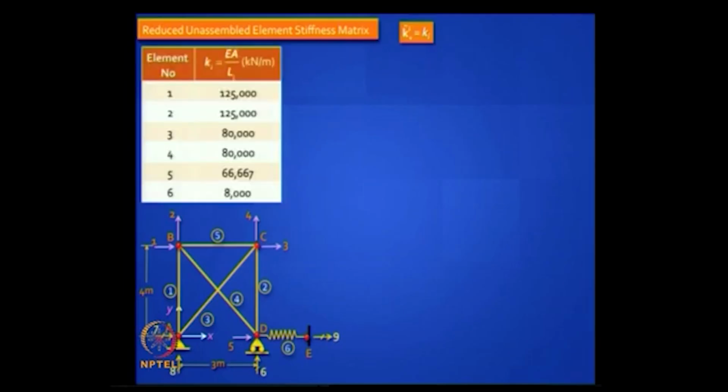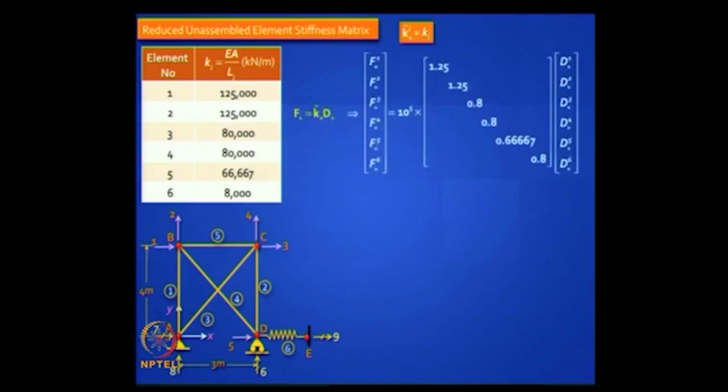So now you have got the TD matrix, please do it correctly, but it is not difficult. Just do a couple of problems, you will get the hang of it. Then you can assemble: you have got the stiffness matrix, you have got EA, you have got L, you can all put it together this way. Is it clear? It is a diagonal matrix. If I have not filled up anything else, it means it is all 0. So this is my K tilde star matrix, okay? Clear? Because you will get it from your axial stiffness for the 6 elements.